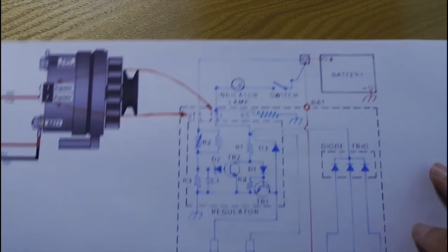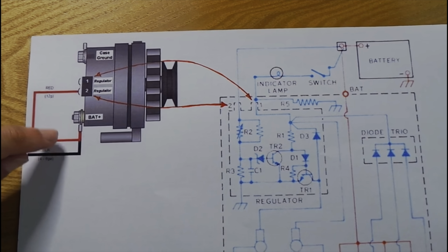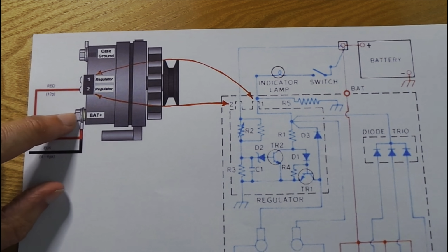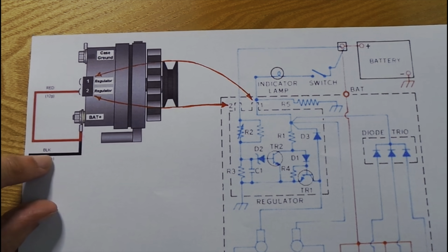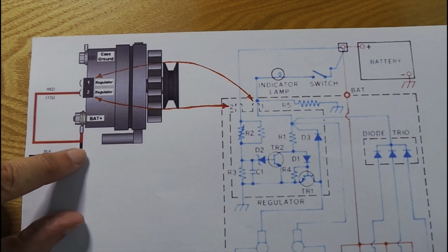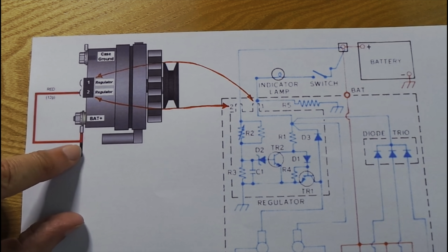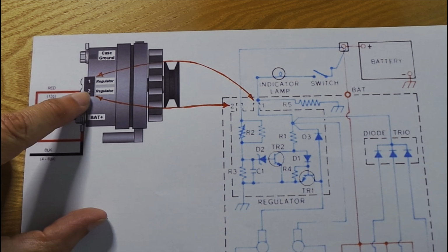Now I did promise, or I did threaten, that I'd say a little bit more about alternators for those of you that really want to know, and this gives us a better picture here. If we look here, you'll find that the alternator will have one thick red wire. I don't know why that's drawn as black on there, that's unlikely, but you'll have a red wire going from the alternator output to the battery, and you'll also have a connection between that battery output and one of the small terminals as well.